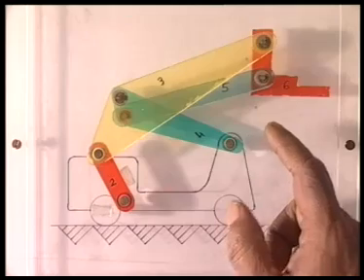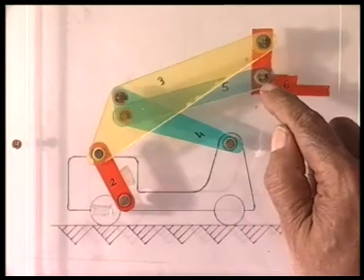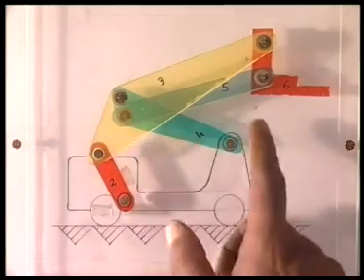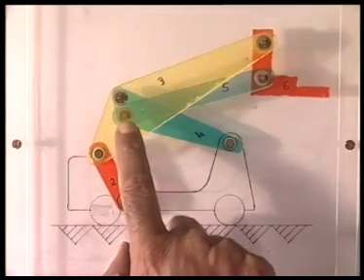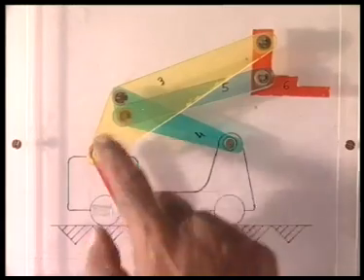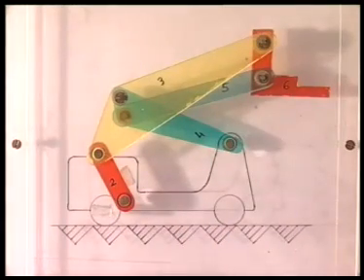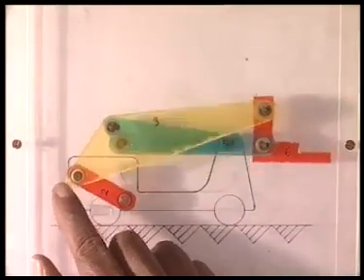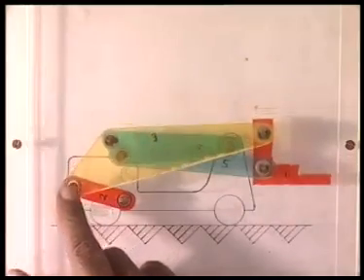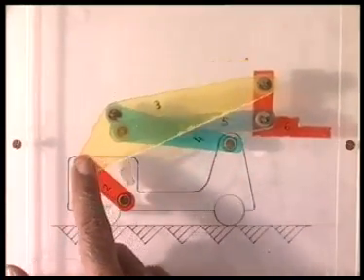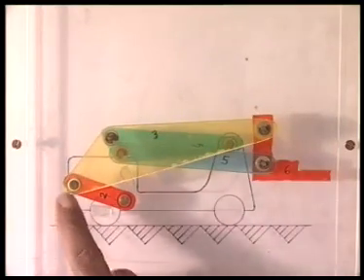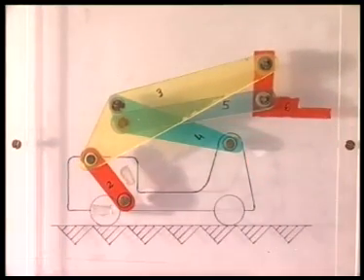And the center of the circle passing through these 3 inverted positions of D, namely D11, D21 and D31, I found the center of that circle at this point, which I called E. Finally, we get this 6-link mechanism where I have a forklifter without any vertical guide. So the techniques that we have learned for function generation, motion generation and path generation can be synthesized together to have a multi-stage synthesis problem for even more complicated problem.